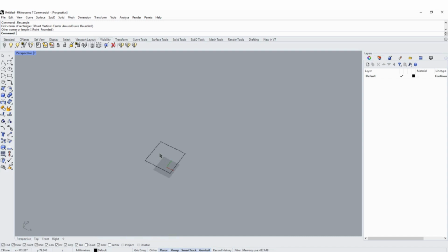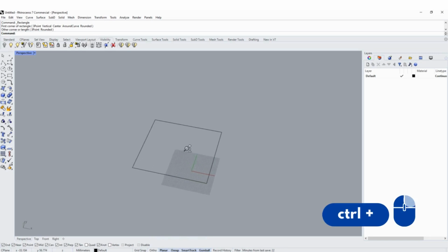Another element that is pretty important is the right click. So let me right click and move around. You can see that my cursor now has changed into this orbit symbol. So right now I'm just orbiting and moving around this element. There is, of course, the option that if you press the right button, the same one that does the orbit, and at the same time press the control, then the cursor changes again and becomes a zoom in and zoom out.